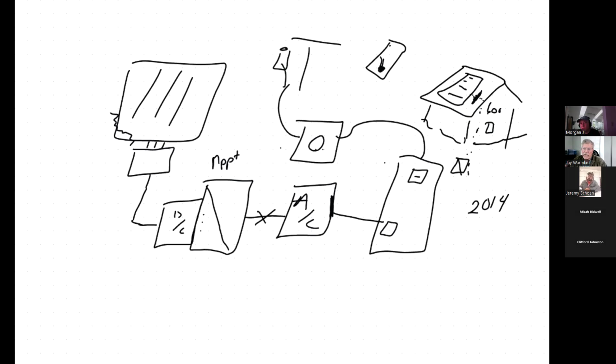It's telling you what it's producing. It's giving you a lot of data. We like that. And people did like it. So you've got the rapid shutdown provision, the anti-islanding. You've got the MPPT. You've got the communication. And then you've got going from DC to AC, all happening right there at the panel. SolarEdge said, well, we'll do all three of those things, the anti-islanding, the communication, and the MPPT, just not the inverter. And we'll call it a power optimizer. And we can produce these things for like $50 instead of $200. So that became another option.